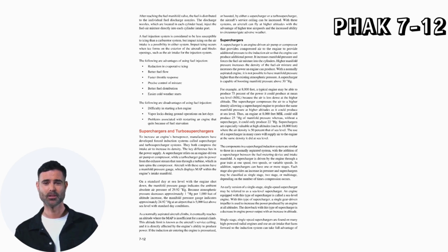Superchargers are especially valuable at high altitudes, such as 18,000 feet, where the air density is 50% that of sea level. The use of a supercharger, in many cases, will supply air to the engine at the same density it did at sea level.